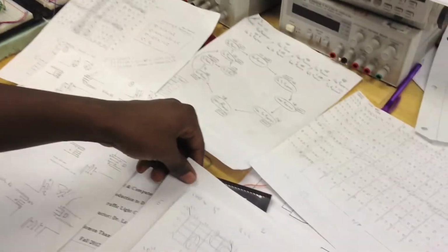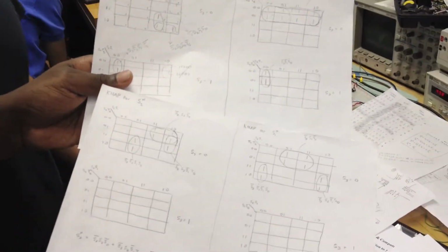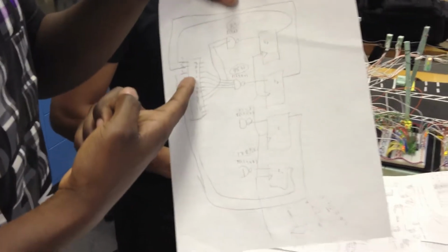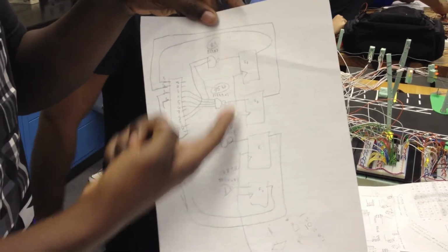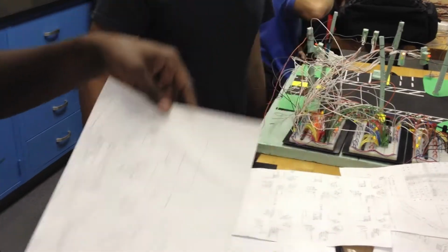Alright, and the first attempt we did to get our excitation equations for our flip-flop was K-maps. At first we did 5 variable K-maps because we were going to do a light sensor, and we realized it was a little challenging, so we reduced it to 4 variable K-maps. And we tried to do it with logic gates, but then we realized that was a little too complicated. So we changed to this design, where we used a decoder going into 4 NAND gates into our flip-flops, and then they were feeding back into the decoder.